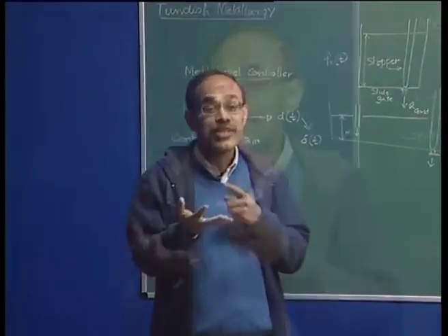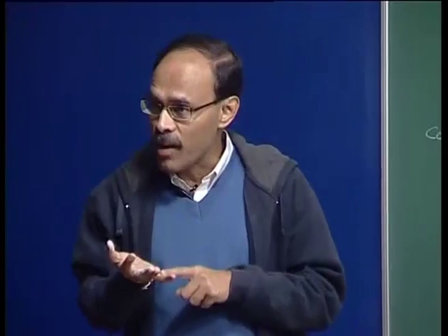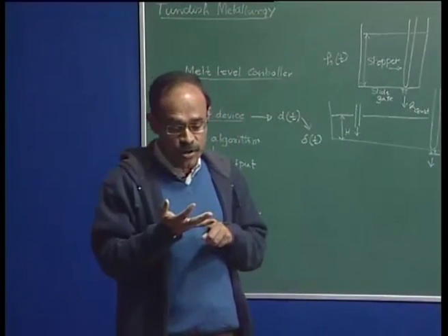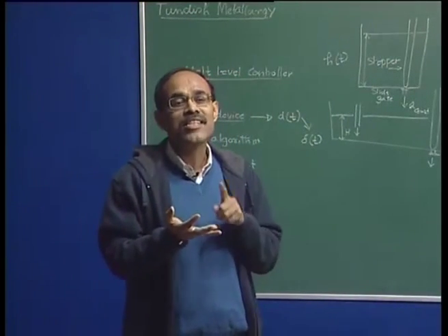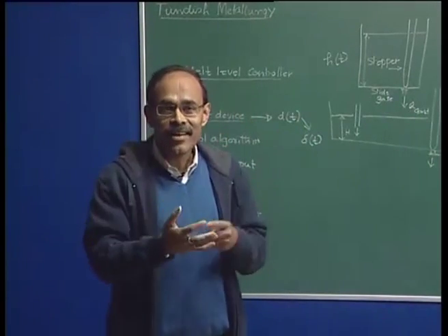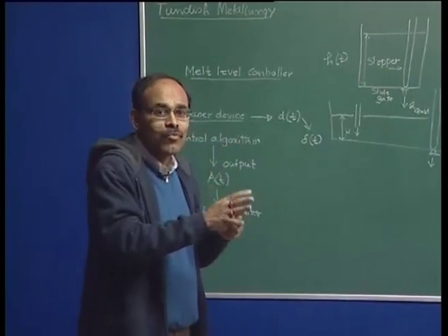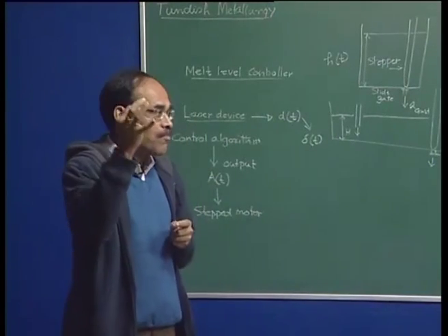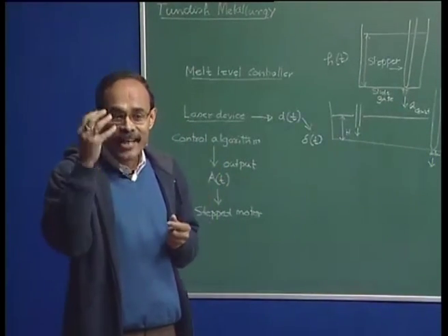First, we have seen deoxidation, and then subsequent to the deoxidation we have talked about inert gas purging, and I have already mentioned to you that inert gas purging is very important because we would like to now create stirring in the process. So, all along one thing in secondary metallurgy is central, and that is the inert gas stirring.